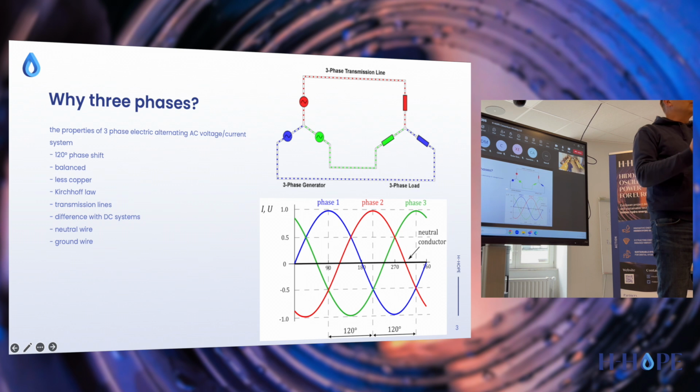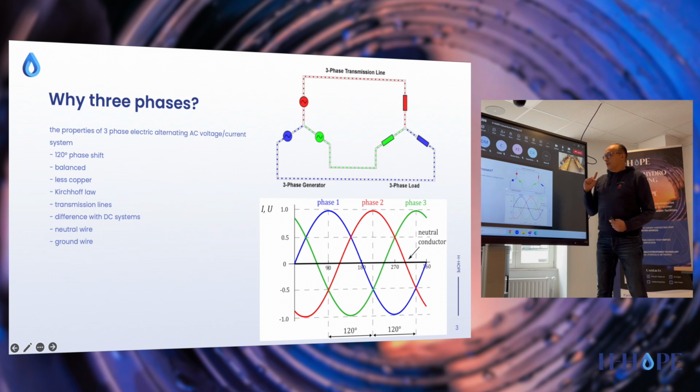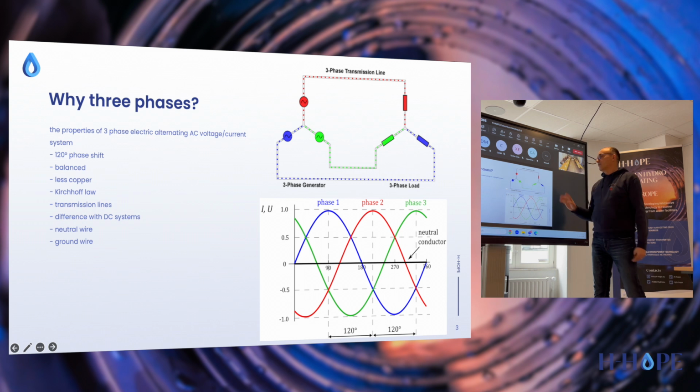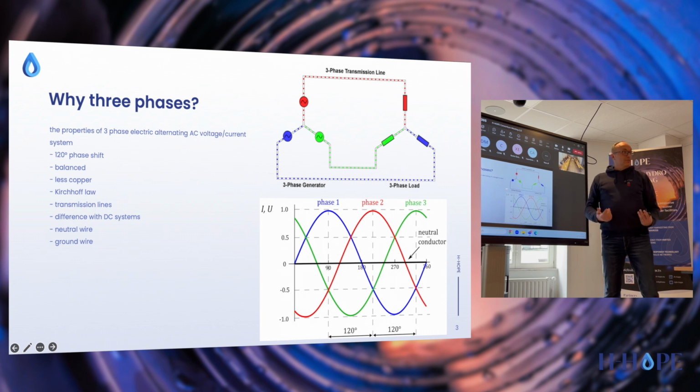And that's the neutral conductor that is in every plug which we have in our room. So neutral and one phase, and the voltage between the two is 230 volts. While if you watch carefully, you will see that between the phases, the voltage is actually bigger. It's not so easy to see because you have to think of RMS value, but anyway, in that case it is 400 volts. So phase to neutral is 230, and phase to phase voltage is 400.